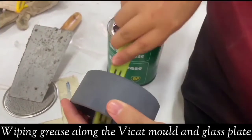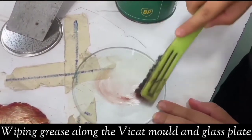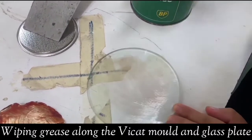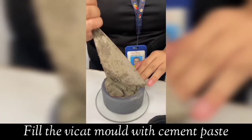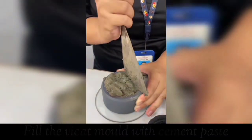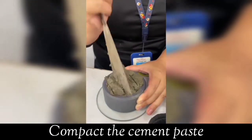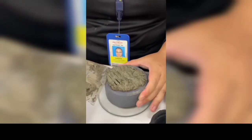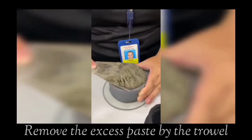Grease is wiped inside the VICAT mold and on the glass plate to avoid the cement from sticking inside the VICAT mold and on the glass plate for a long time. The VICAT mold is filled with cement paste, which is placed on the glass plate. Ensure to compact the paste well after filling the mold. Fill the cement paste to the top of the mold. The excess paste was removed by the trowel.